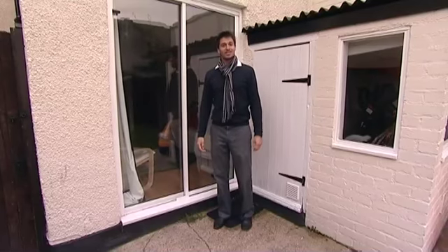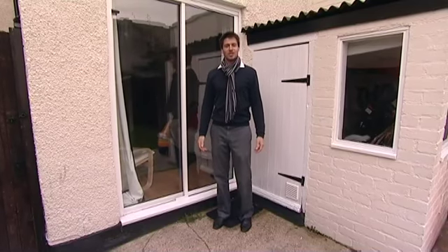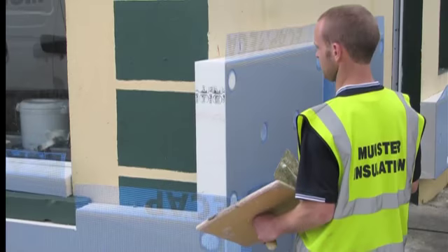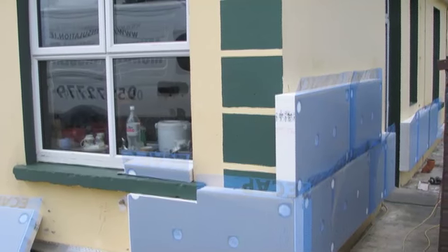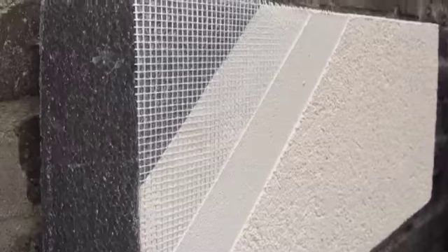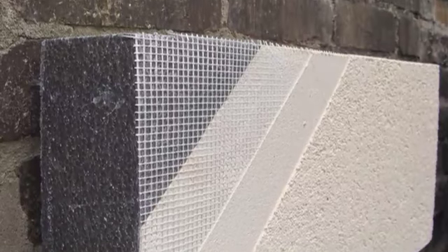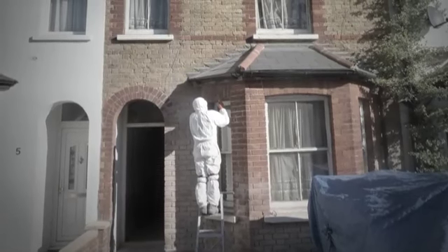As the name suggests, external wall insulation is fitted to the outside of a property and should only be done by a qualified professional. It's done by fitting a layer of insulation material to the walls with mechanical fixings and adhesive, and then covered with a special type of render or cladding. The final appearance can then be finished in whatever style suits. Smooth, textured, panelled or even a brickwork finish.